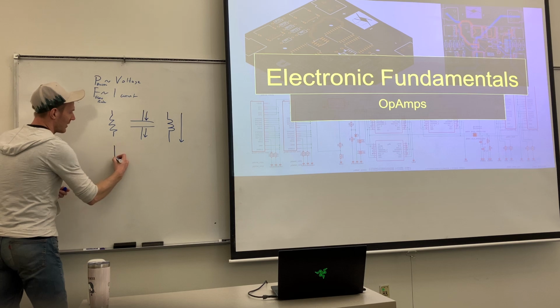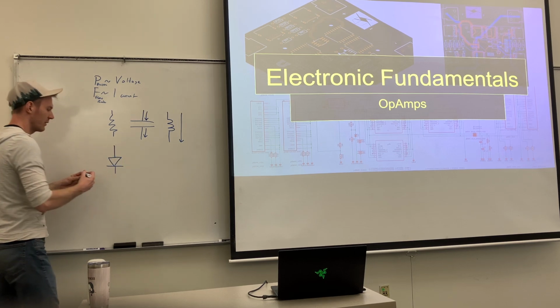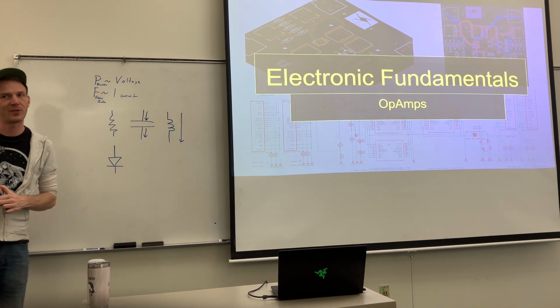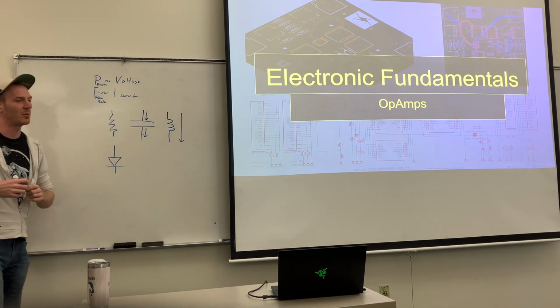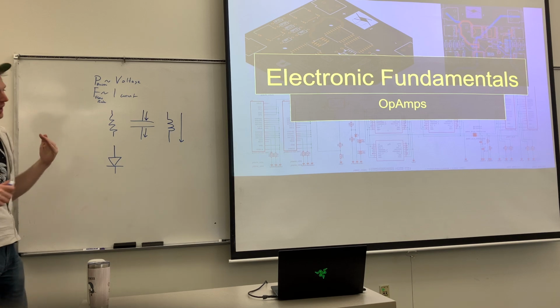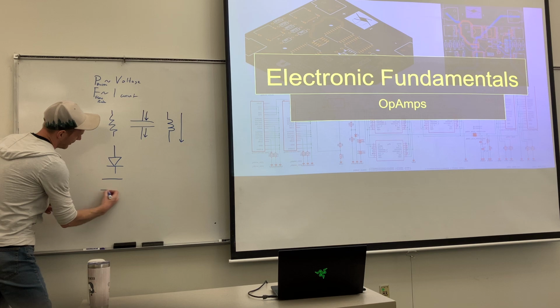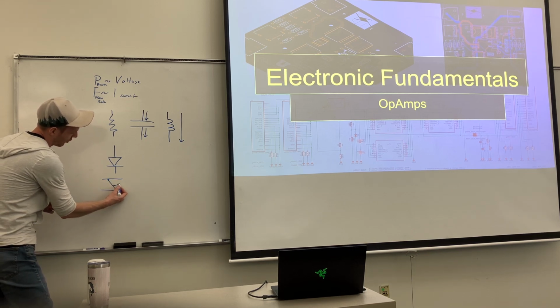Then we talked about diodes. Diodes are basically the mechanical equivalent of check valves, but I recognize that probably not a lot of people have a whole bunch of fancy valves at home. What you need to remember is they just allow current to flow in one direction. A check valve has a big flapper right here, and it can only be pushed open this way.